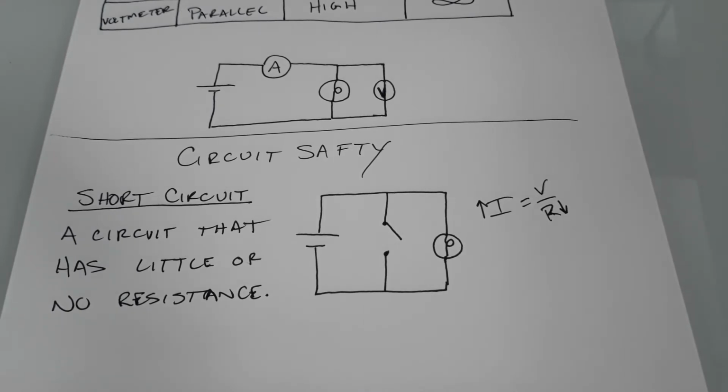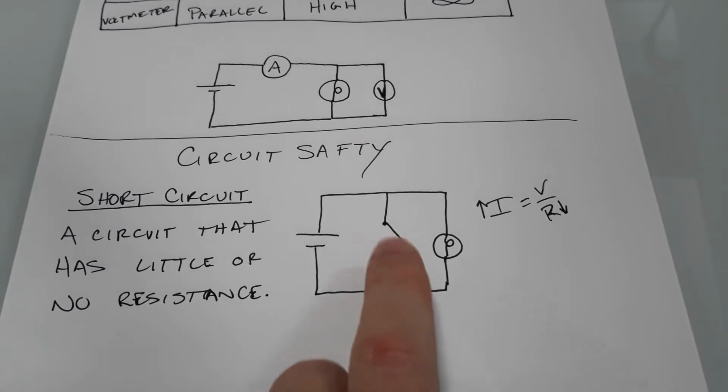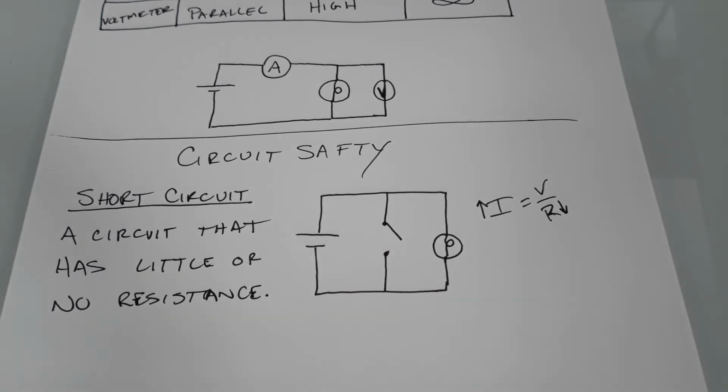But look, if the wire gets super hot, then the steel conduit will also get very hot. And so the potential danger that the dust will catch on fire is very great. And this has been the source of many, many fires when electricity was first becoming common in people's homes. They would pull too much current. They would either create a short circuit, or they just would draw too much current, and that would cause the wires to get so hot that they would start a fire.